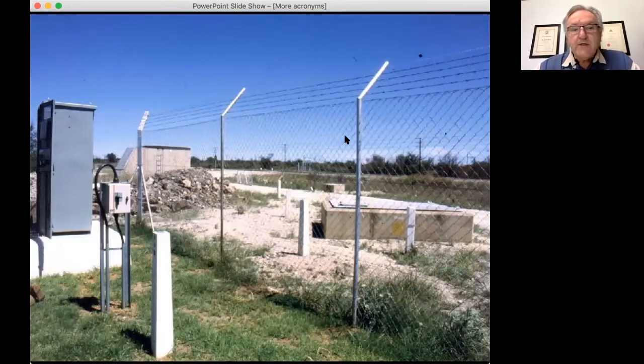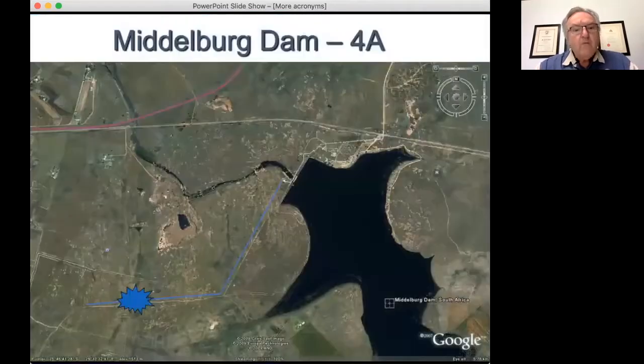On the right-hand side over here, we saw that there's a rail, and there is in fact about a 200-meter long cable going from the rail back to the pipeline, or rather the other way around. We tend not to use forced drainage units because they can cause more problems than they solve. We also have the situation where the pipeline is nowhere near the rail.